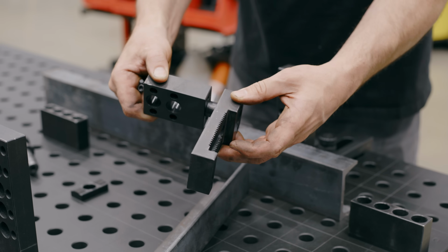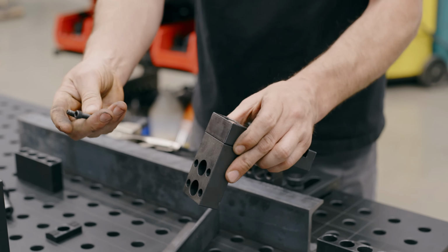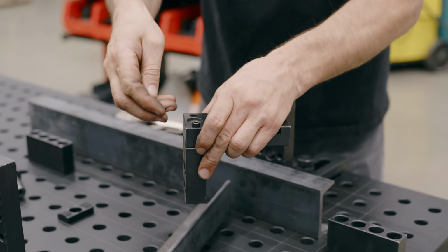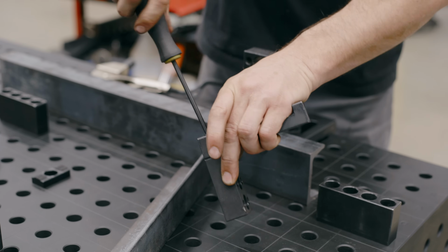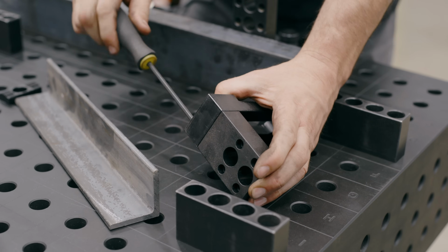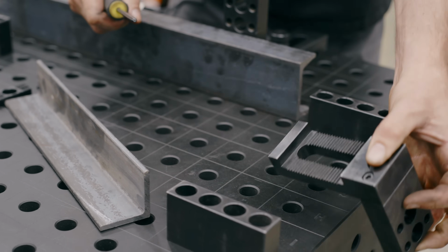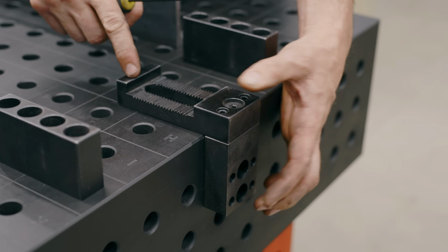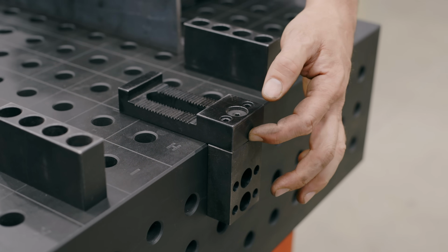This is why I like the Fireball system, is we can configure it just about any way we want. Pivots, but now we have these 2 screws that lock it in position and keeps it square. And then we just quickly add them together with the screwdriver and we suck everything up tight, and because they're all machined, everything lines up really good. And we have a nice square part. There's no teeter-totter. It's perfectly 90 because these are all machined components getting bolted together.